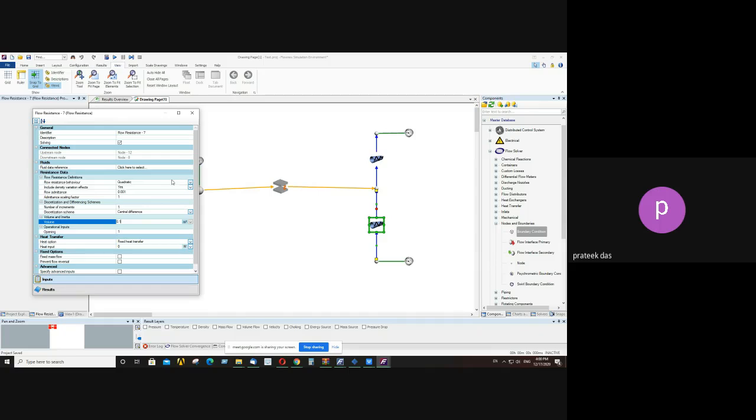So you can specify this behavior as quadratic, in terms of square; linear, in power of 1, so there will be no square; and square root, so that the power is reduced to half. Basically, you can only specify the amount of resistance it will provide to the flow path. In our case, we specify the flow resistance as 0.001 and the volume of this component as 0.1.